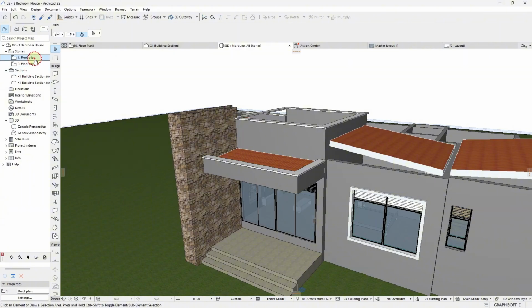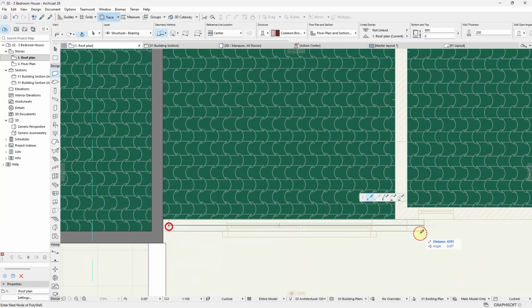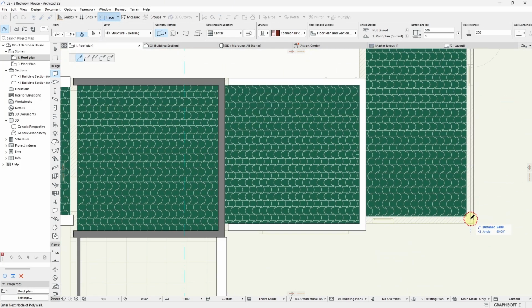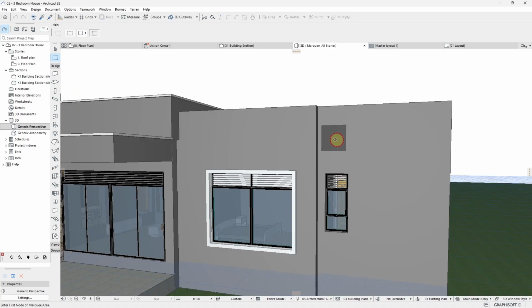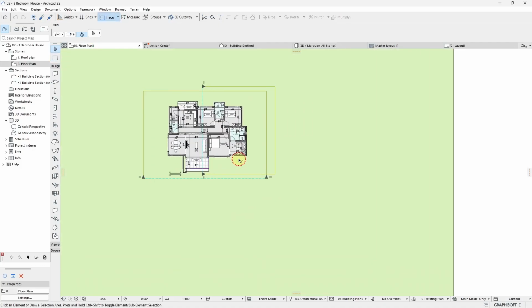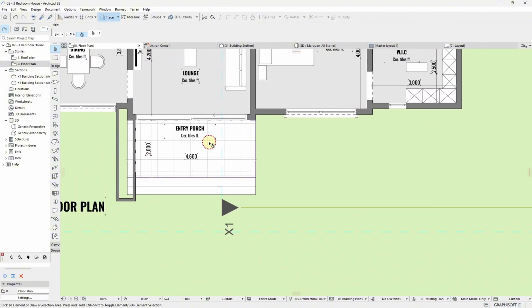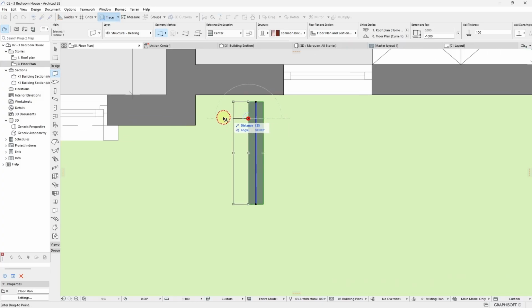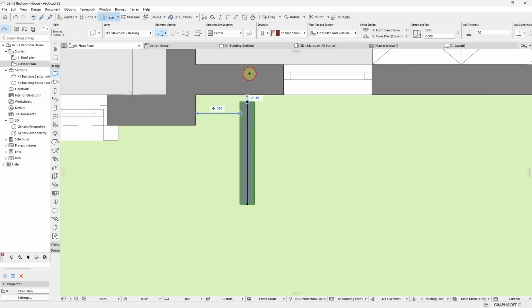Okay, so I'm also going to go on my first floor up and I do a parapet wall. So one thing I'm going to do is I'm also going to provide a duct here to drain this water out. What I need to do is now we're going to have an issue here because I want to have my duct at this exact position. So I'm going to put my valley here. So I want this to be like 300 millimeters off. And then I'm going to make it 600 millimeters wide.